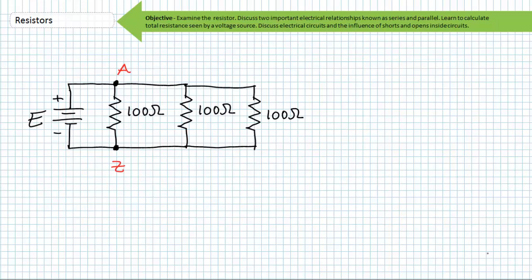33.33333 ohms of resistance. What if I put 100 100 ohm resistors in parallel? You guessed it. With 100 times the cross-sectional area, you see 1/100th the total resistance, because there's 100 100 ohm doors for Johnny Electron and all his rowdy buddies to crowd through. In this case, the source would see only 1 ohm of resistance, and chances are it's cranking out a lot of current because the total resistance is so low.